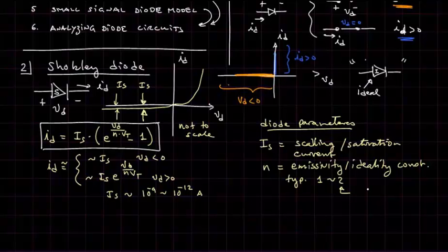When we have discrete diodes, a discrete diode is a diode you can actually pick up in your hand and it has 2 leads on it, typically the value is around 2. When the diode is part of an integrated circuit, then it is closer to 1. That's related to the physics and the properties of the semiconductors and the fabrication. So when it's inside an integrated circuit like a microprocessor or an op-amp or a driver circuit, then N is closer to 1, but that's the range of it.